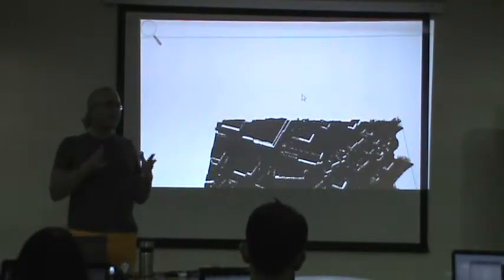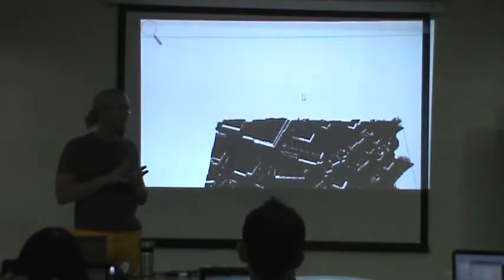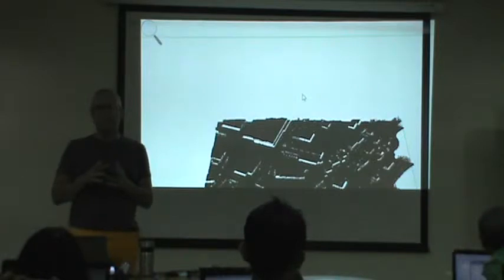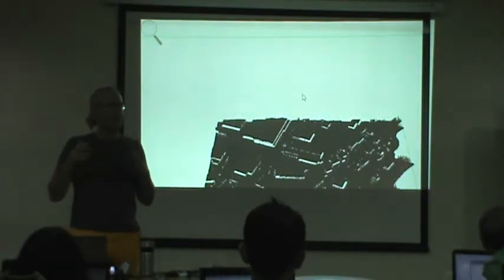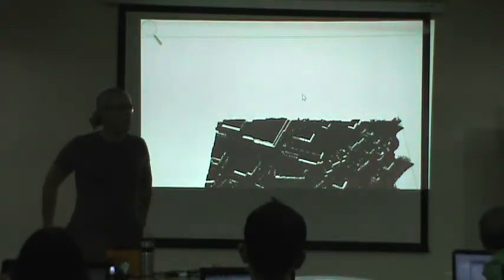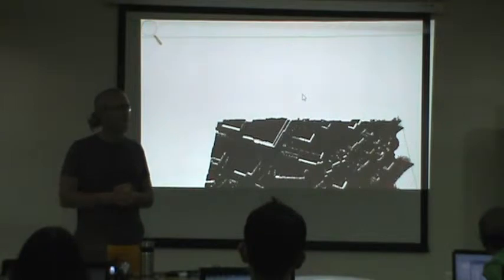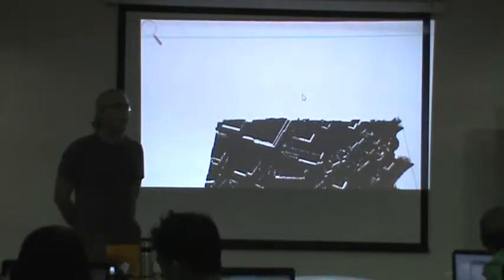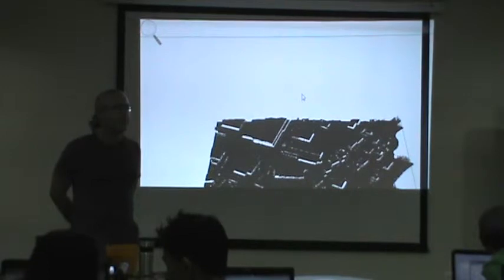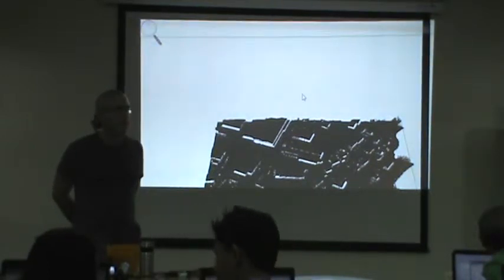If it doesn't work for you, then several options. There is somewhere a space in your path. That's the most common error. You installed it like my space software, and then you install either QGIS or LAStools or something there. It's not a good idea. Use the default location to install QGIS, but more likely the problem is with where you have installed the LAStools toolbox.